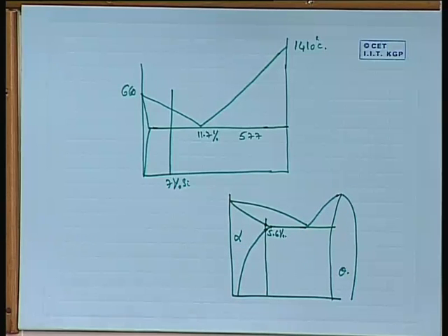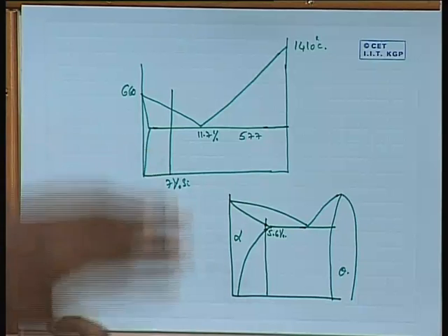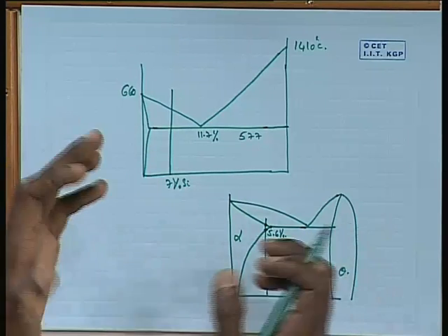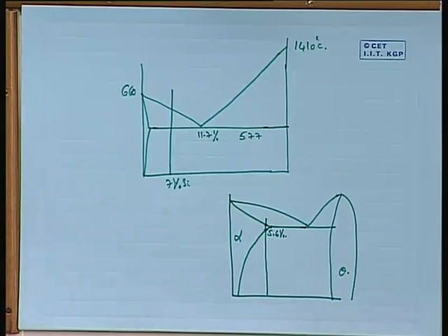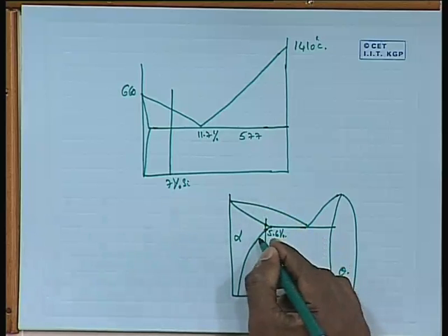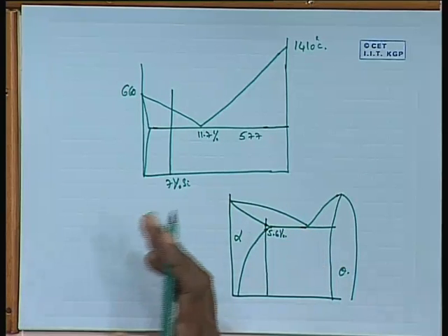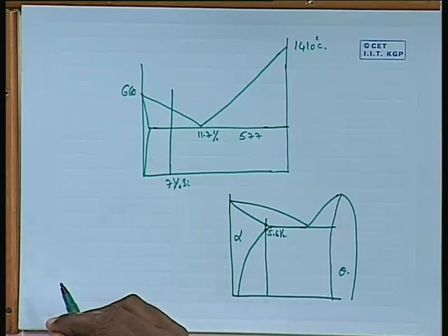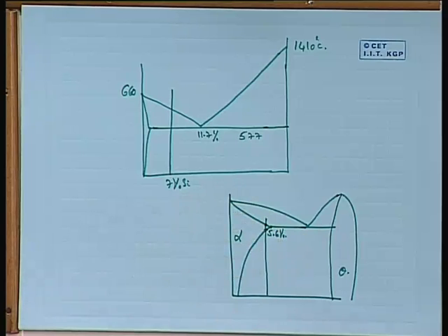What is the basic goal of solution treatment? That you want everything in the form of one single phase having a uniform composition, and that you want to quench it to get what is called a supersaturated solid solution. As a result, one does not usually go beyond about 4.5%. That's more or less the maximum. Similarly in aluminum lithium alloys, usually about 3% is the limit that we use.